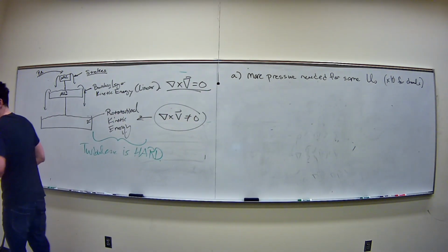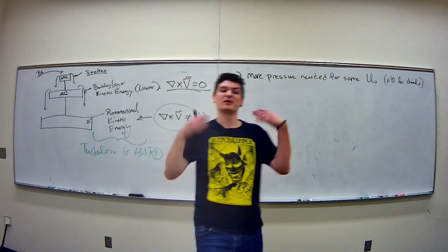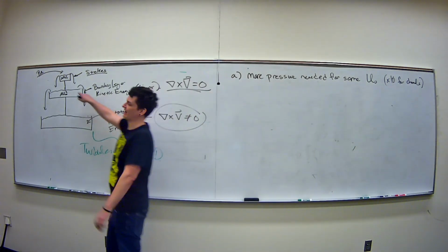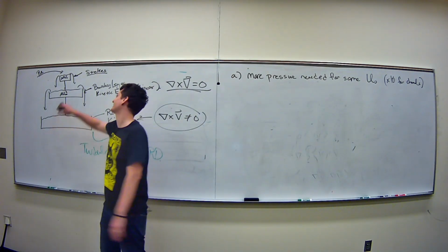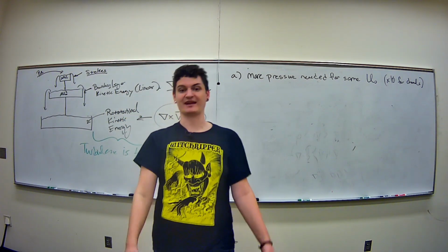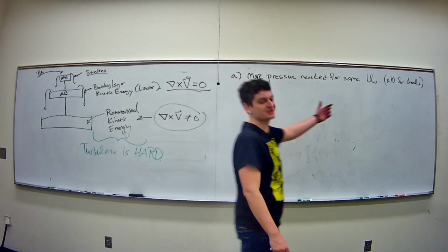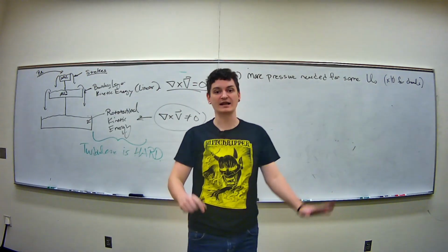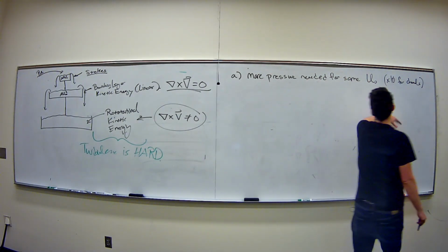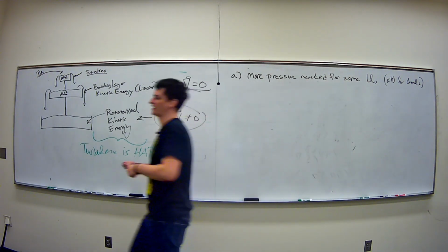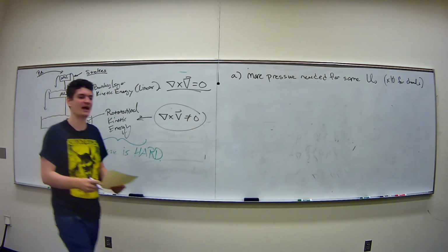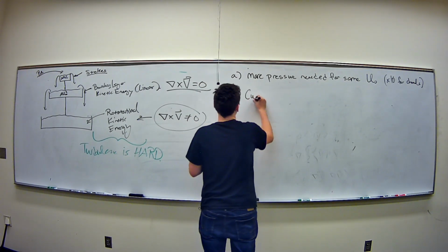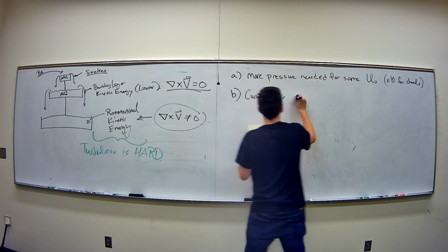How can you always remember that statement? Well, like I said, the more you're driving it, the more you're trying to flow this fluid, think of it as this cascade of energy. I didn't tell you about cascade, but think about it that way. You're driving a lot of energy in there, and then if it's turbulent, a lot of that energy is just going to be wasted into the rotational parts of the flow, not going linearly down the pipe like you want it to. So it makes sense that you're going to need a larger pressure gradient to get what you want in turbulent flows, because you're spewing it away into those pesky rotational parts of the flow.